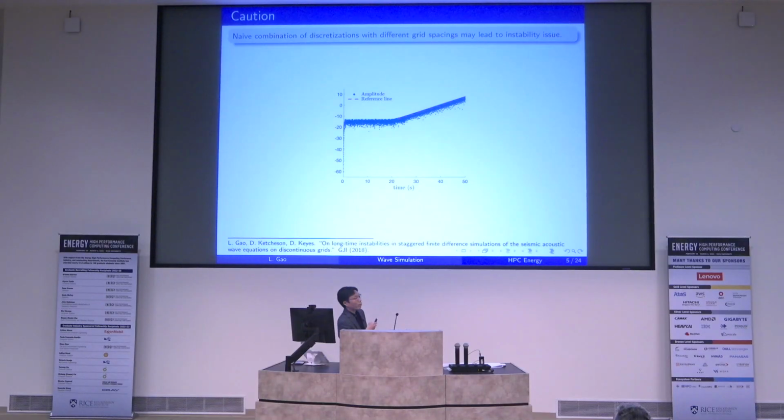The red one is a reference line whose slope corresponds to an eigenvalue. The eigenvalue is coming from, I would say, the propagation matrix. You do your spatial and temporal discretization. You have your solution at one time step. You have your solution at the previous time step. They're linked together by a propagation matrix. And now we have a purely algebraic problem. You take that propagation matrix, you do an eigenvalue decomposition. That eigenvalue essentially tells you whether the corresponding eigenvector is going to increase in amplitude, decrease in amplitude, or stay the same as you progress forward.